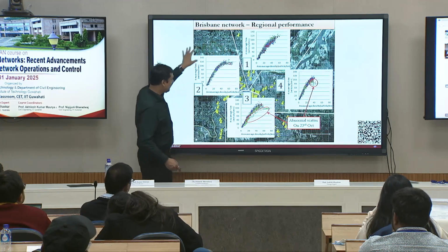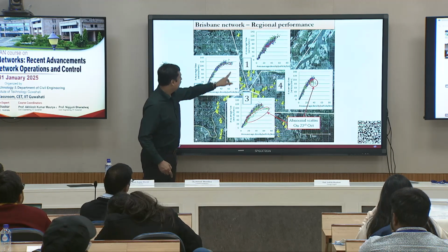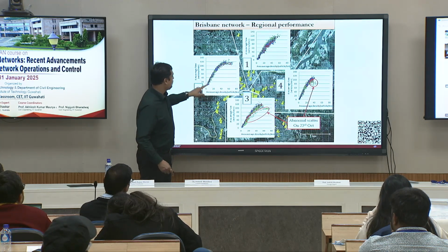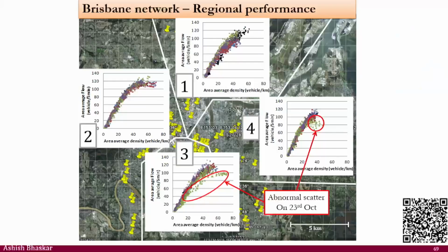If I look at this whole area for which I have drawn the fundamental diagram, around this specific time, let's say the slope is 120 by 60. How much is that? 20. Average running speed is 20 kilometers per hour, which is what you observe in the arterial network anyways. So the slope is the average running speed for the entire section, and that is the space mean speed for the entire area for which you have drawn your mesoscopic fundamental diagram.